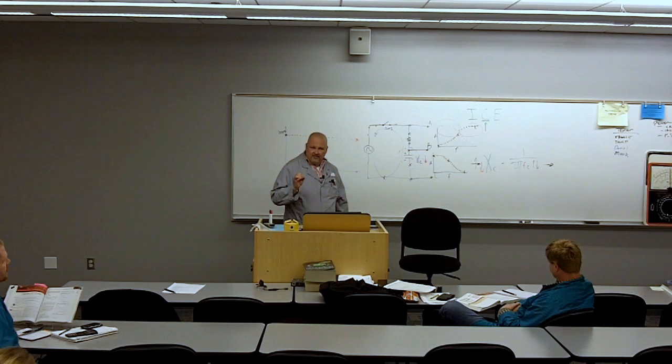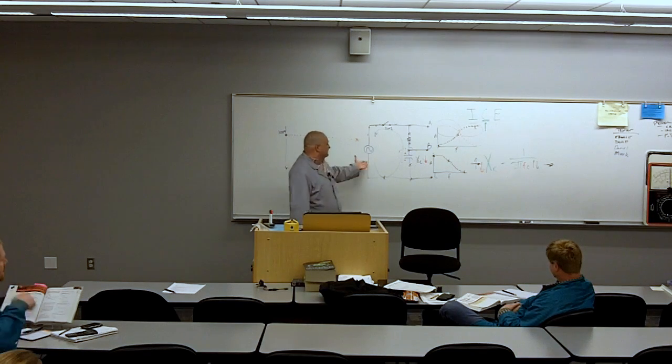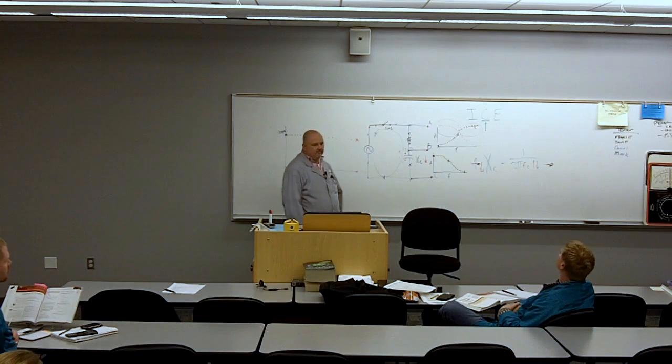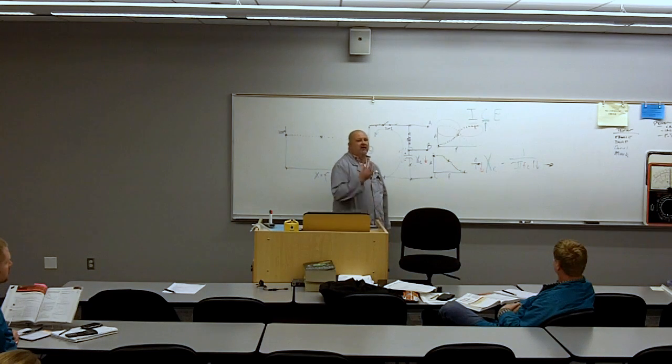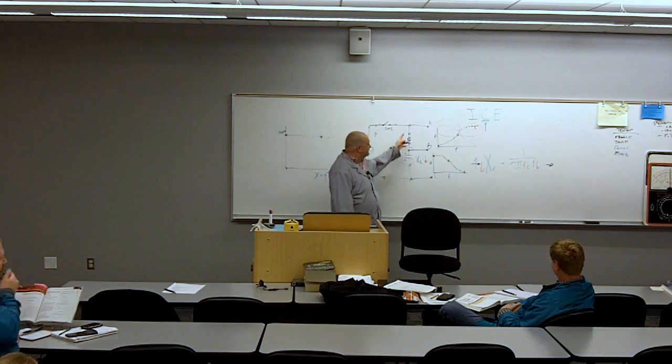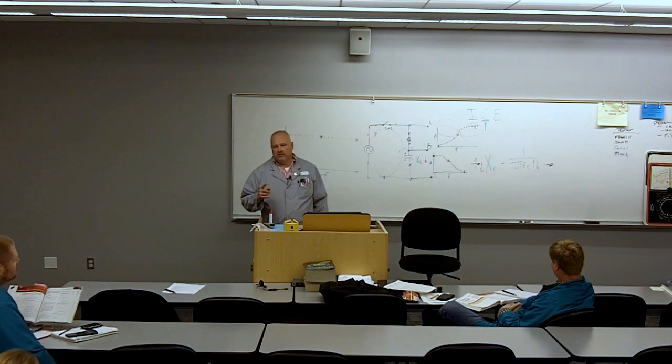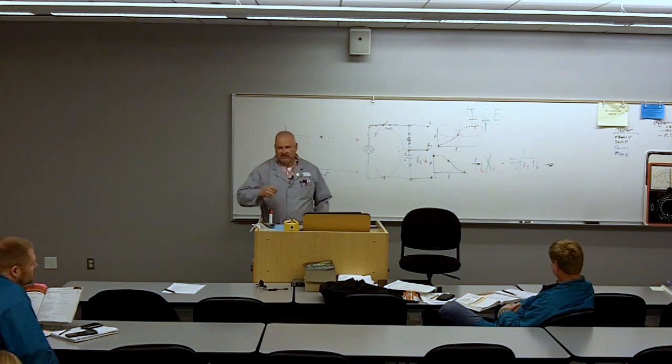Does that make sense? This whole chapter is one formula, and if you embrace that formula, everything else that I showed you, series circuit, series RC circuit, AC series RC circuit, you should be comfortable with that. Current's constant in the series circuit. The series circuit is also known as a voltage divider. If you want to harness the voltage that's being developed, you need to connect it in parallel with the output, or connect the load to the parallel component. This is the parallel cap, this is the parallel resistor. Do not deceive me, or you'll get it wrong in the quiz. And then you'll be challenging the man, and the man will have no sympathy.